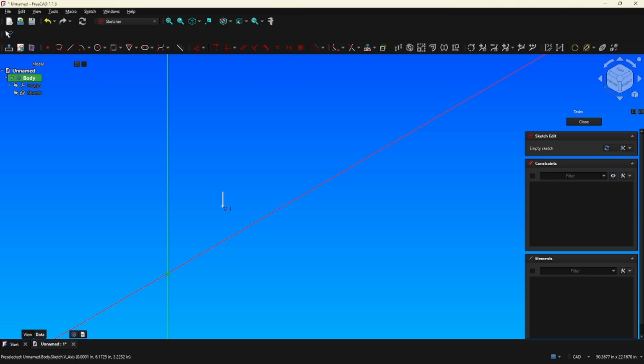There's a vertical constraint you see right there, horizontal, another vertical. You can see the horizontal constraint showing up there. You can see the constraint where it is attaching to that line, coincident to that line. But if I move it over slightly, I should get a vertical constraint as well. There you go.